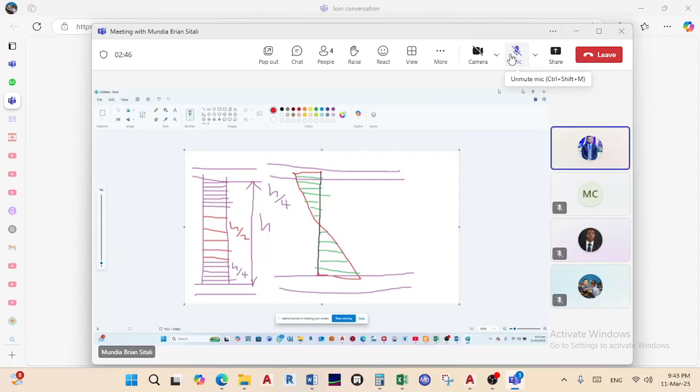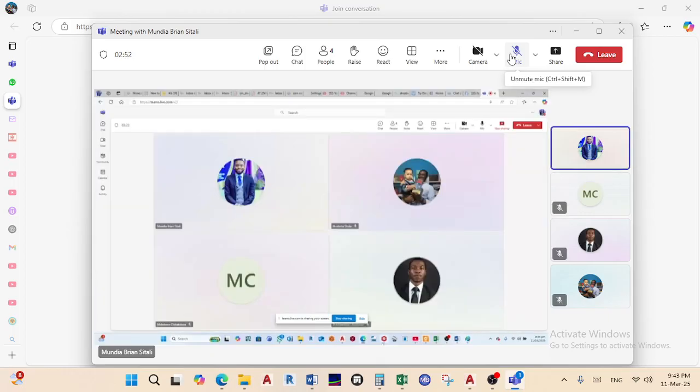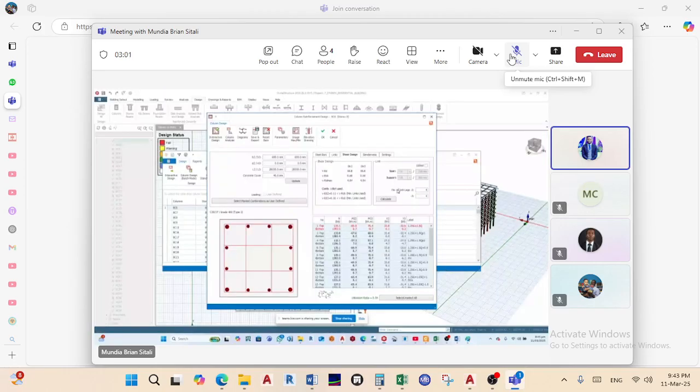So the reason why I had to draw this is because of what I want to do here. So I'll minimize this, go back to Prota. You've seen here, you can easily just say, okay, 200 to go. And then you say where you have span, you use the h/2 value. So you leave it at 200. Then on the support, I usually drop it manually down to 100. So you can do 100 or you can do 150. For some reason, yeah, 100.